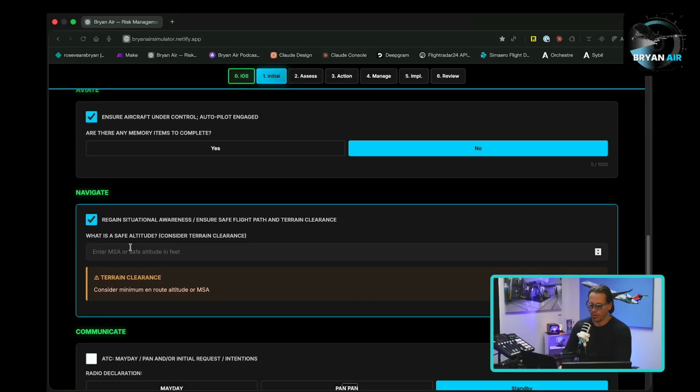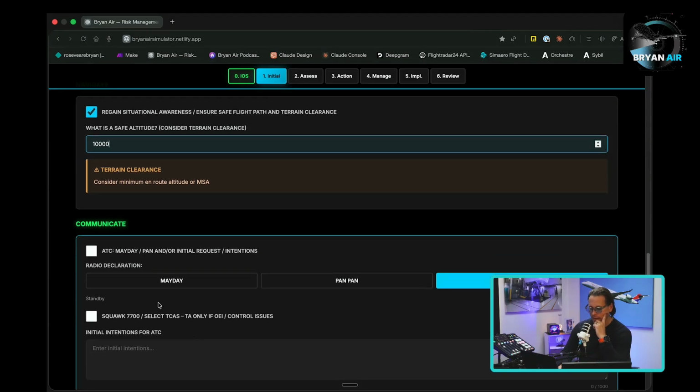So, nice to know what your MSA is there. I'm going to say 10,000 feet. There is some rather high terrain over there. But the idea here, from a practice perspective, is to go and open the JEP and have a look at what your MSA actually is, where they are. But I would say about 10,000 feet would be a decent altitude there. Not that you're going to descend randomly to that altitude, but we do have a pack problem, so we might need to. And then communicate.